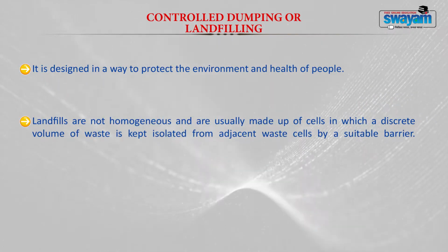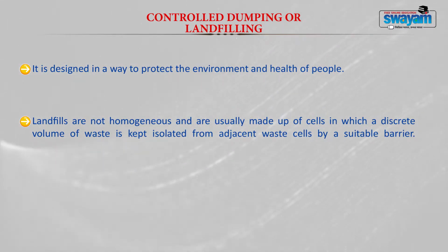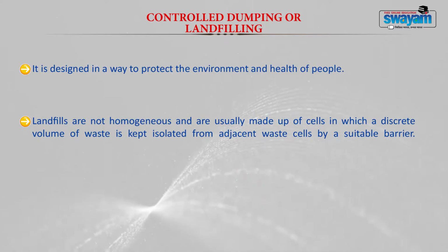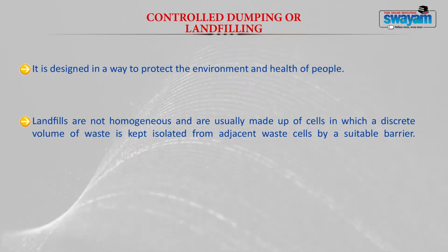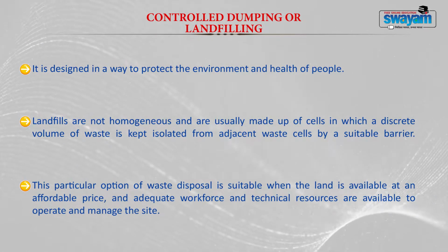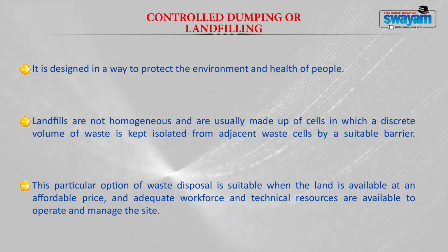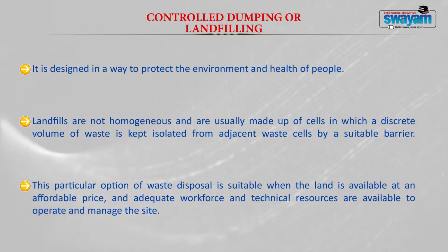Now, landfills are not homogeneous, they are usually made up of cells. As I mentioned earlier, here the waste is loaded in a systematic manner. It is not haphazardly placed, and it is not homogeneous. Here the waste is placed in cells, where a discrete volume of waste is kept isolated from the adjacent waste cells by a suitable barrier. This particular option of waste disposal is suitable only when land is available at an affordable price, and you have an adequate workforce and technical resources. If these three things are available, then you can go for a landfill option.